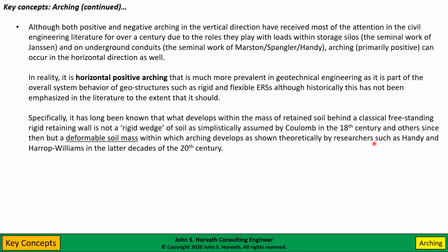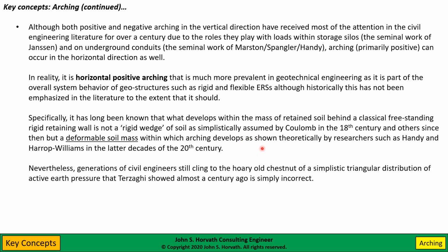And this has been shown theoretically by researchers such as Handy and Harrop-Williams in a variety of published papers in the latter decades of the 20th century. But despite this, countless generations of civil engineers still cling to that hoary old chestnut of a simplistic triangular distribution of active earth pressure behind a retaining wall, even though Terzaghi showed almost 100 years ago that it is simply wrong.